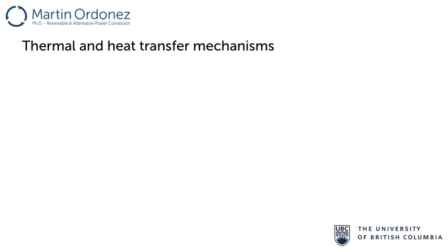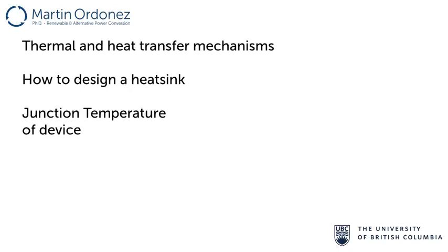Today, we are going to talk about the different heat transfer mechanisms, focusing on thermal conduction. We will also see how we can analyze its effects on the thermal design of power electronic devices, such as heatsink design and selection. Our goal is to solve a common power electronics problem from the thermal point of view, determining the steady-state temperature of the junction of a device when employing a specific heatsink.